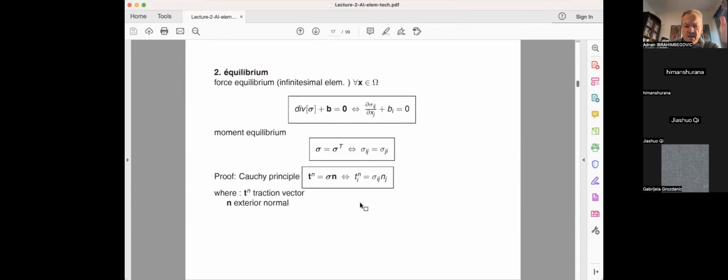Basically, you have the possibility of writing the stress vector on any particular plane that you might need. So the idea is that this Cauchy principle was the way of extracting the stress vector components for any plane that we need. And this is the first result where the notion of tensor appears. Unfortunately, it's a lowercase letter, but what can you do? It's still a second order tensor.